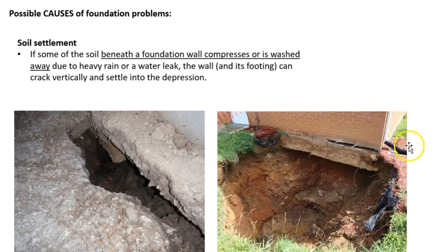So a very inexpensive but important component of the house is the downspouts. The house collects a lot of rain up on the roof. It needs to be brought down by means of the gutter system and downspouts. And then here, this little black extension to the downspout should be moving that water away, at least 5-10 feet away from a house at the scale of a residential property.